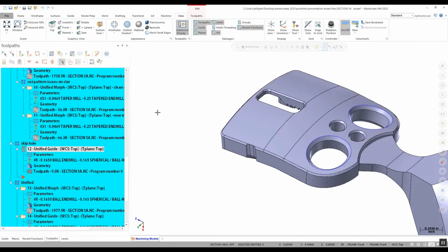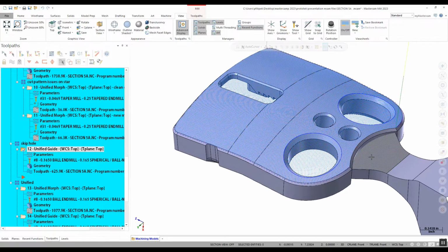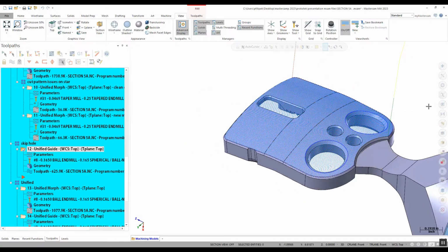And there we go. I had that tool path locked. So now we'll get some calculation out here. And now I get nice smooth motion. So I mean, I got one entry, one exit, and I got smooth transition over all them holes, making all the difference just by turning on one quick little switch there in the parameters.